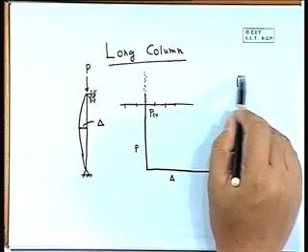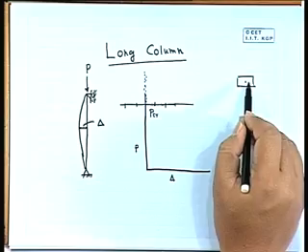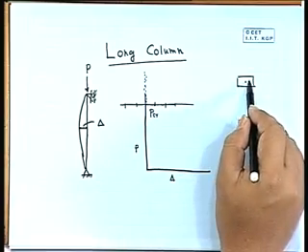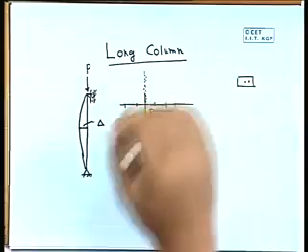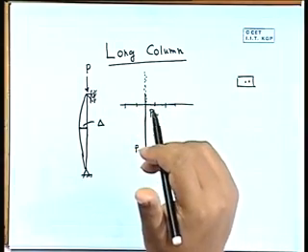Now, this is the load deflection curve for an absolutely perfect column. Now, if I say the load is not acting at this point, if I draw the column section here, it is not at the centroid, it is a little bit away. So, what will be happening? If the load is shifted, there will be a bending moment.